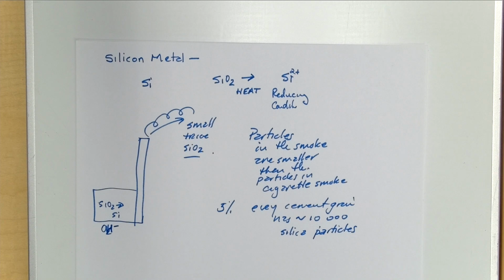Because silica fume, the particles are so fine that if you took silica fume in a jar and you poured it out here, it would kind of hang in the air because it's a smoke. Silica fume, the silica smoke, is what we call it. There's lots of it made whenever you make computer chips or ferrosilicon steel, which is a very particular type of corrosion-resistant steel. Silica fume is also a pozzolan, but every one of these particles has a surface that needs to be coated.